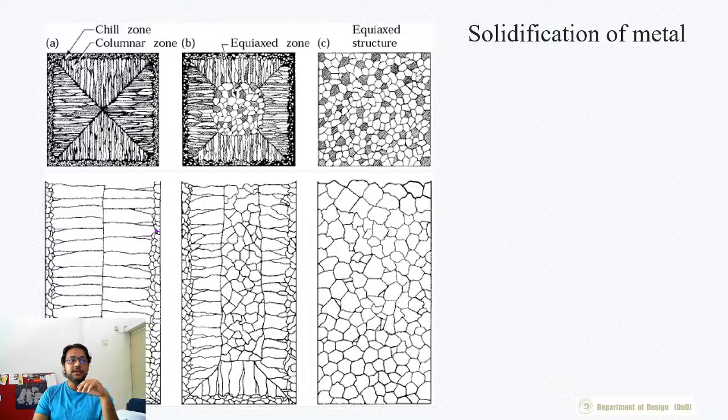If that temperature difference is very high, then despite this insulating layer of solidified material, the internal material will still lose a lot of heat very fast, and because of this, these columnar structures are formed, and the columnar structures kind of join together when they cool down, and they form this kind of shape it is observed.